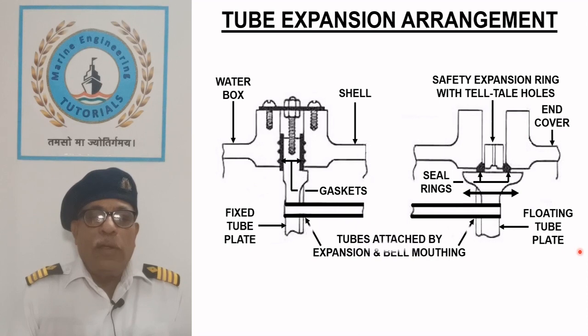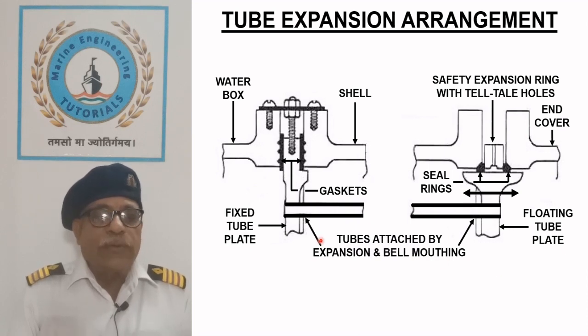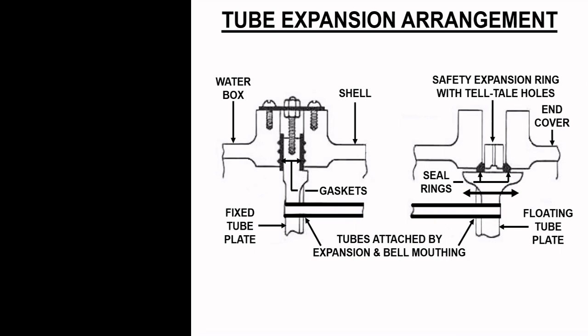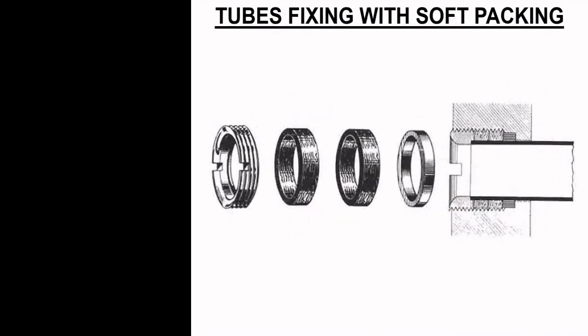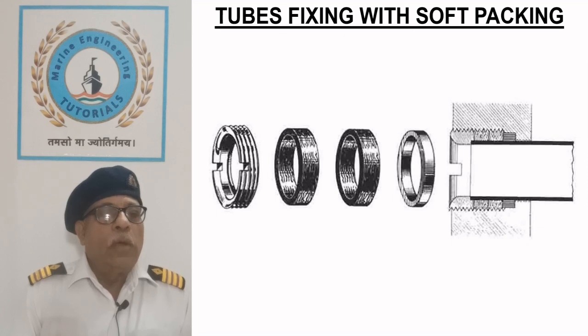Tubes are usually attached by expansion and bell mouthing, although another method which is not so common is described on the following slide. Tube fixing with soft packing.